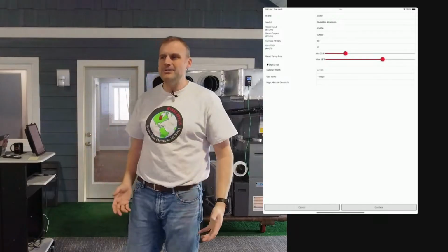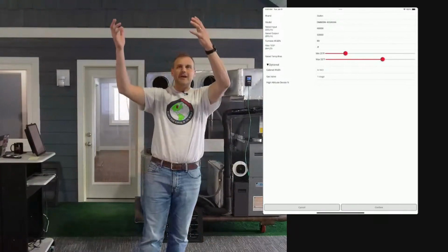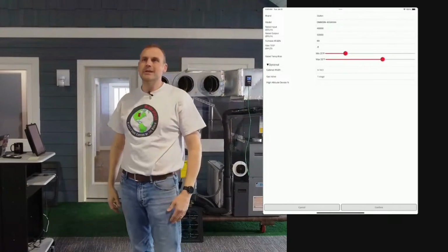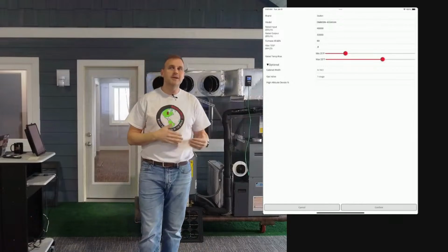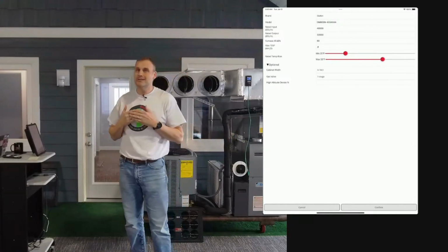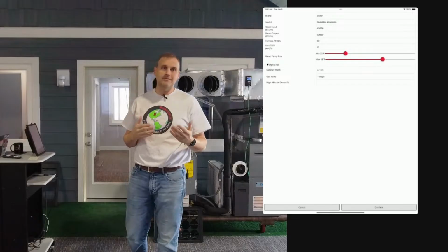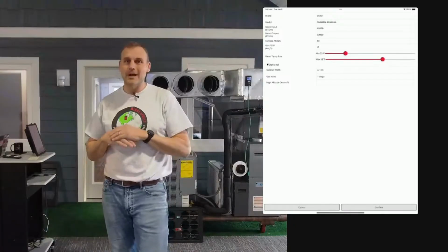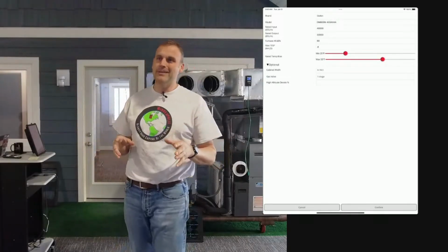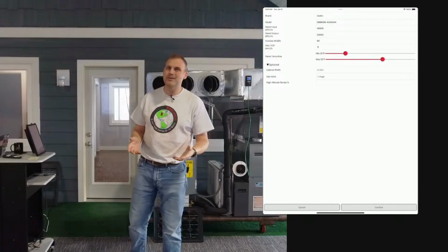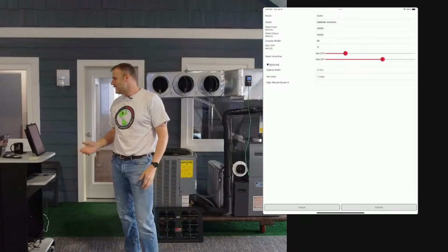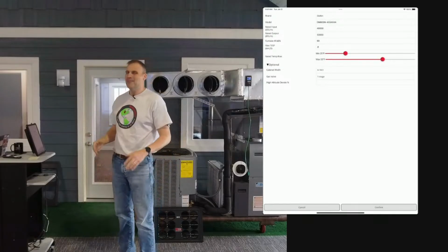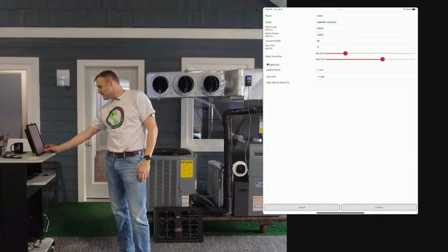So derate, so as you take this furnace and you move it into high altitude situations, like Denver, Colorado, or going even higher to Breckenridge, the manual is going to say something about derating that furnace, and it's a percentage, and it is not the same across the board of all furnaces. I wish it would have been, because then we could have geotagged it and solved that problem for you. But I read a ton of manuals, and I found out that it's not always the same, which means it has to be a user input. So you got to go chase that data point down. If you're not in Denver, or anywhere around Denver, you're probably okay. So basically, leave it blank. Okay, we're going to click confirm.